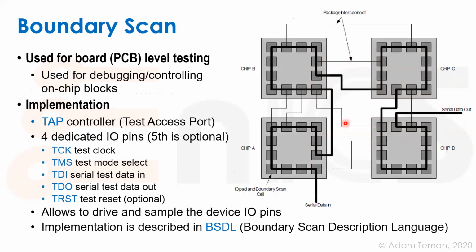So boundary scan is something like this. What we're going to do is build the same type of scan structure, but instead of going through the flip-flops in the design, it's going to go through the chips on the board.